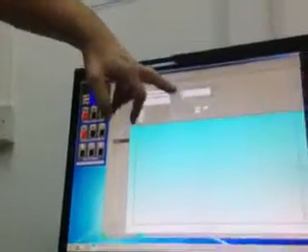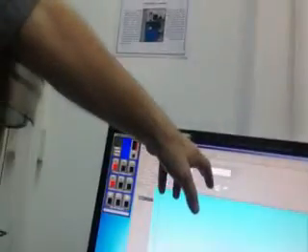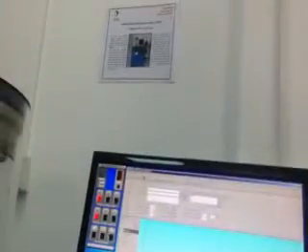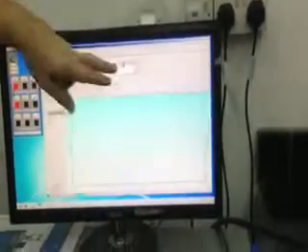This next section is where there's specimen information. If you're doing a number of markings on the sample, you can measure heights at different points and then enter in the diameter and height here. We'll give you an average and a standard deviation. If the sample is not very level and you're getting a standard deviation past the tolerance, then you may have to reject the sample because you need to be fairly level. So you can use this to check how good your sample is prepared.